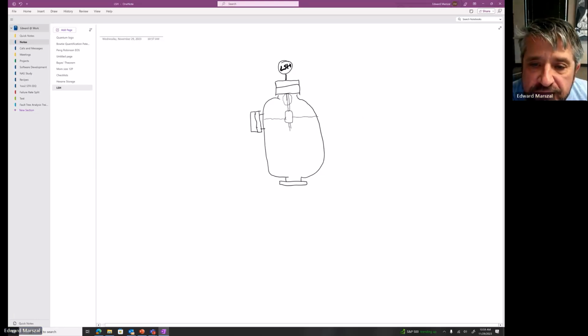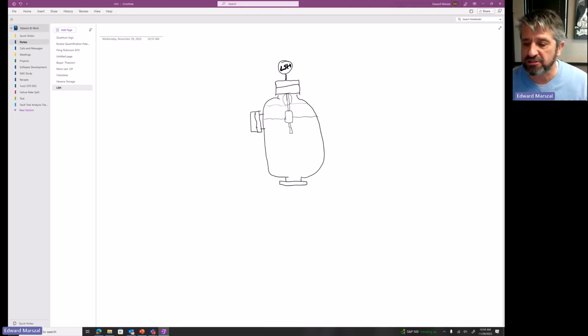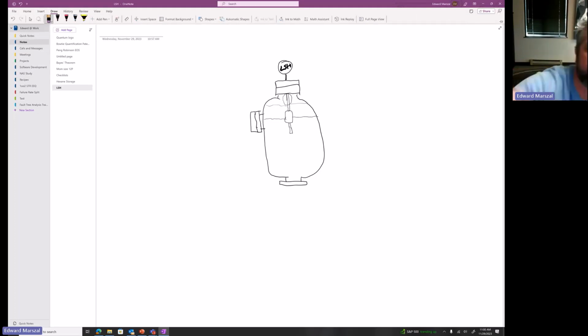Now when I want to test this device, how do I do it? How do you perform a test of this device? Some people might say, let's just keep filling this vessel until it reaches the trip point. Whoa. Actually, testing an SIS by generating an actual real live demand on your process is kind of crazy. People don't do that, and generally they're going to want to test this during the turnaround. So how do you do this kind of test during a turnaround?